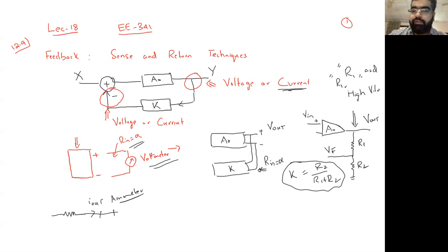In reality, you put a very small resistance here, the current flows through this very small resistance, and you measure this potential. By measuring this potential, you can find the current. So V divided by a very small resistance will tell you the current. And it should be very small so it doesn't affect the actual resistance of the circuit. So in this case, you ultimately measure the current of a simple system.